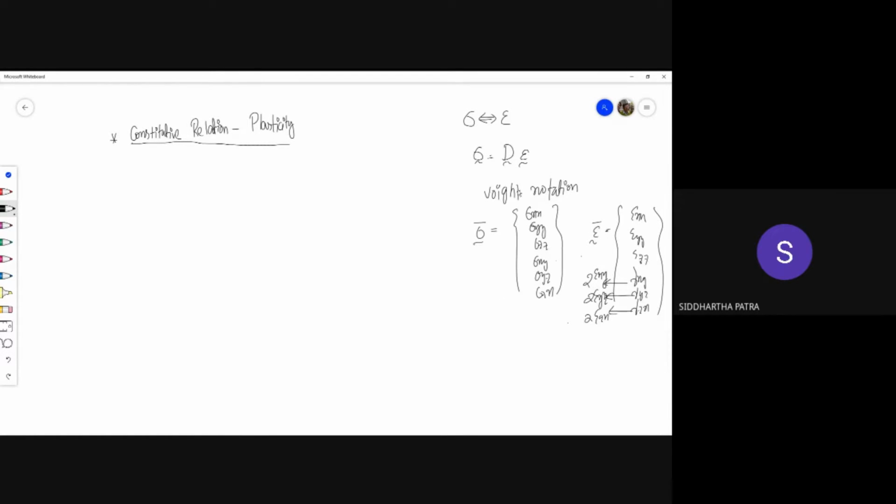Okay, but this coefficient of two serves this purpose, that when we, let's say, if I want to do the inner product of stress and strain. Now this time they are represented as matrices. So this quantity would be summation over i, summation over j, sigma ij, epsilon ij. So basically you take each component of the total 9 terms, 3 times 3, 9 terms of sigma, and take the corresponding component of the strain, multiply the two, and keep adding those products. Okay, so that is what this term means. So this is like the inner product of the two matrices.